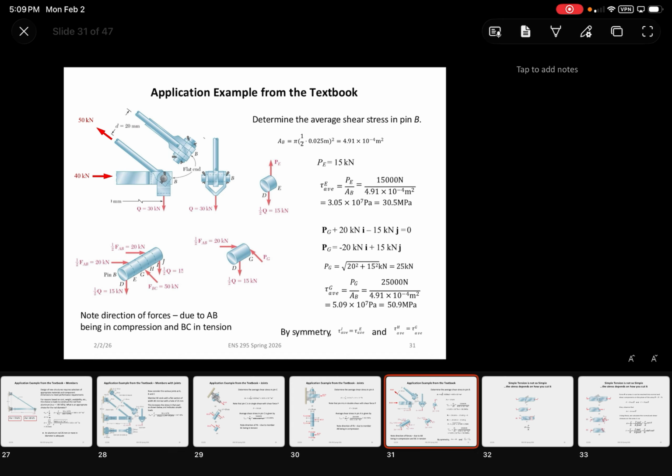Yeah. So for the bearing stresses, let's basically use this as kind of an example, right? You could see that D, D prime, and E, E prime are shear planes. So those are where shear stresses occur. Now, this example didn't cover bearing stresses, but when you have a system, these pins are undergoing bearing stresses also, which is entirely just bearing along these surfaces here. So to find the bearing stress is just a type of axial load directly along the surface.